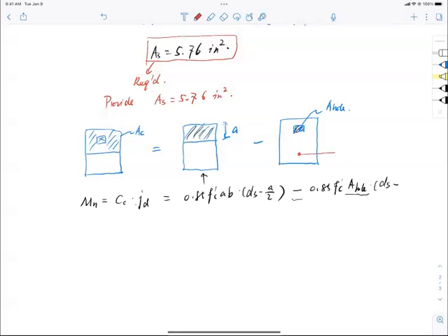Reinforcement is that ds, and this is so-called JD2, and let's call it JD1. So JD1 naturally equals this distance right here, and JD2 equals ds, which is the depth, minus this distance right here. So this is 2 inch of a gap given, and this is 2 inch from the top of the opening to the center of the opening. So 4 inches. This is ds minus 2 and minus, sorry, 2 minus 1 again, because the height of the opening is 1 inch.